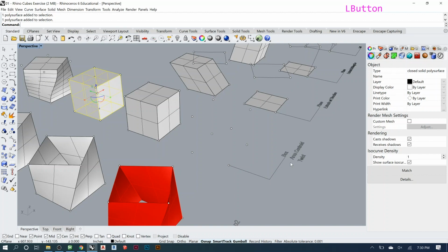In this sense, it's a weird way to grab the center point. But think of a really complex surface, like the back of these chairs. Imagine each one of those diamonds has a center point somewhere, right? But you can't just draw one and copy it over to all of them. So it would be nice if you could tell Rhino, find the center point of all those and put a point there for me. Then I can scale all of them down towards the center, or scale all of them up. You can use this a lot with panel systems because you want that center point.